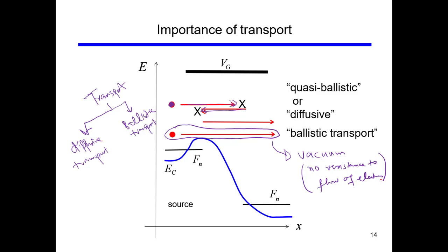Okay, so let's stop our discussion here, and this is to summarize. This was the lecture about the virtual source model, which explains the velocity saturated IV characteristics, and we have seen how we can smoothly connect the linear and saturated regions. We have also seen how the resistance in the saturated region can be included through the DIBL effect.